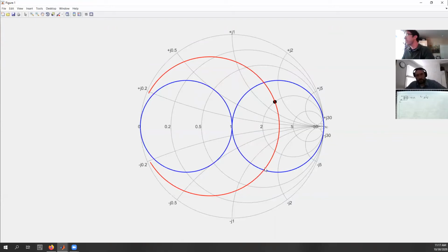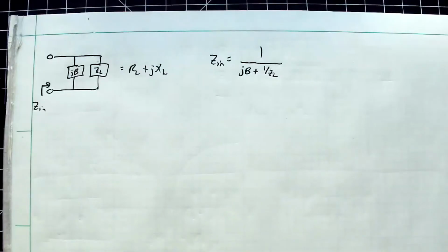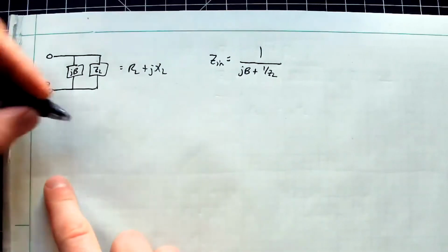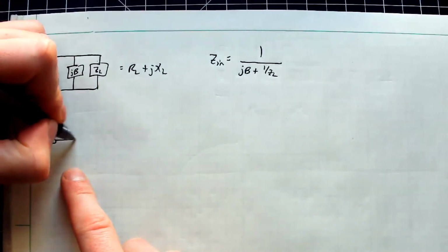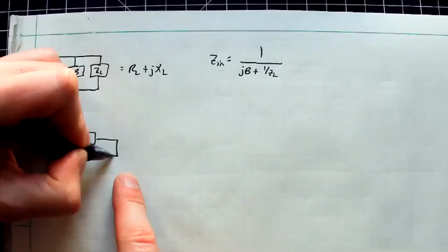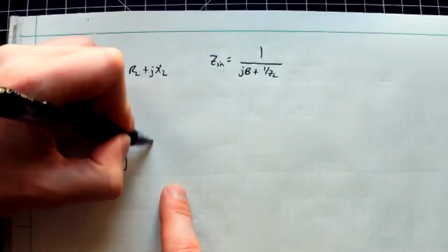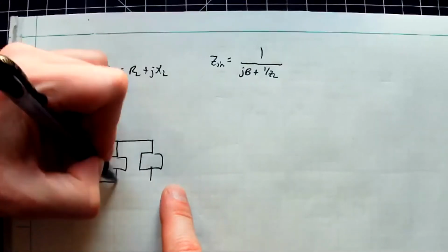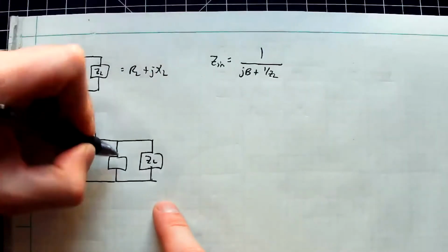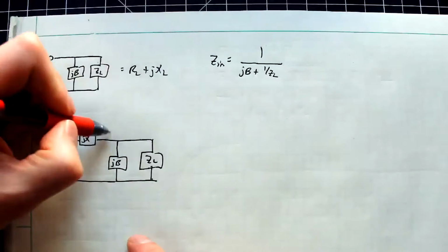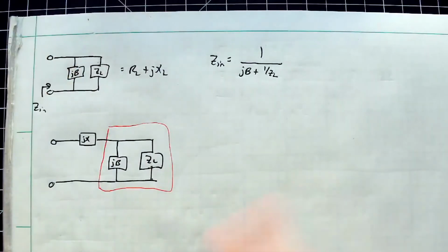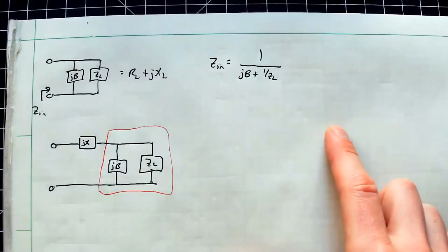And then you'll notice once I dial to one of these points, I just have to add the appropriate series value here. So let's stop sharing again. We'll go back to here. So the end result looks like the following. I have some series value here, and then I have the shunt, which is the technical word for it, like so, okay? So there's my ZL, there's my jB and jX. So the idea is this little block here will follow the circles on the left, right?